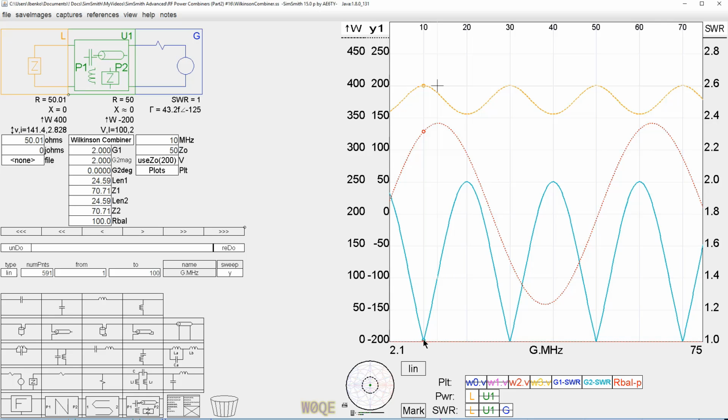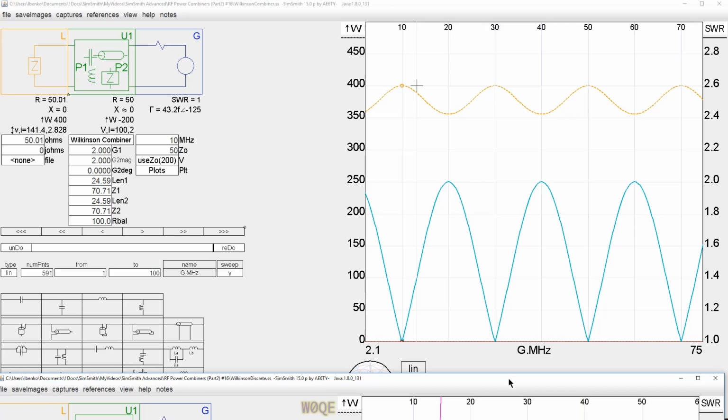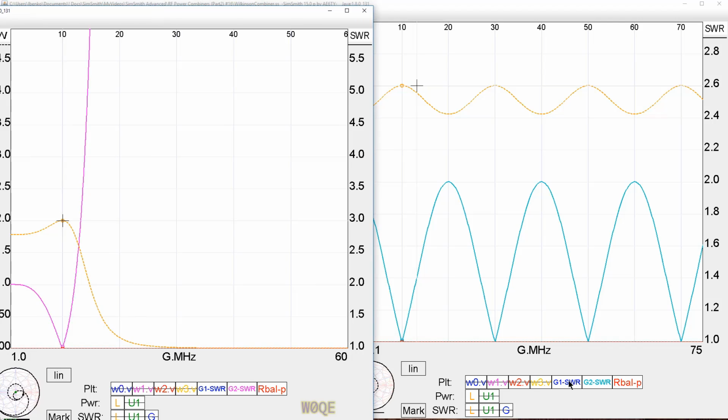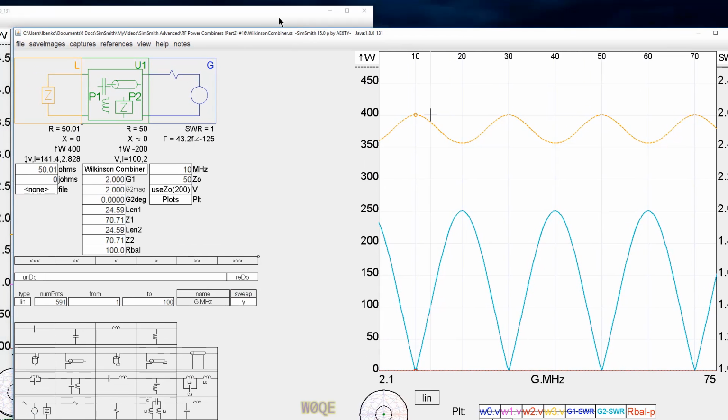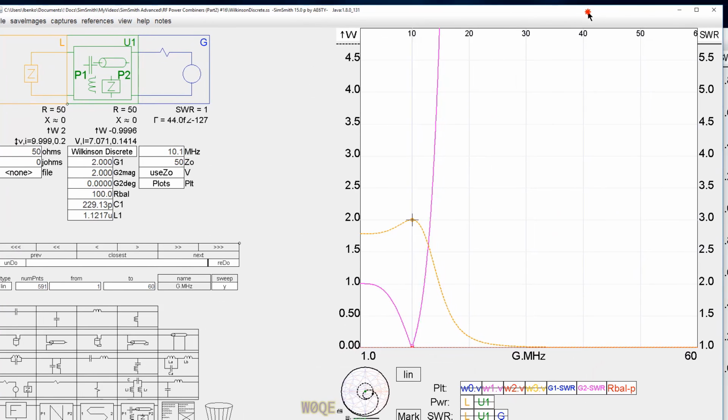What we have here is the length of the transmission line is a quarter wavelength, 3/4 of a wavelength, 5/4 of a wavelength, 7/4 of a wavelength. And as long as there's no loss in the transmission line, it operates exactly the same on all those frequencies. The other circuit doesn't do that. And if we look at the SWR on these two, it's hard putting both these on at the same time. This is a little bit narrower SWR bandwidth than this is, but not much. This is a perfectly reasonable solution.